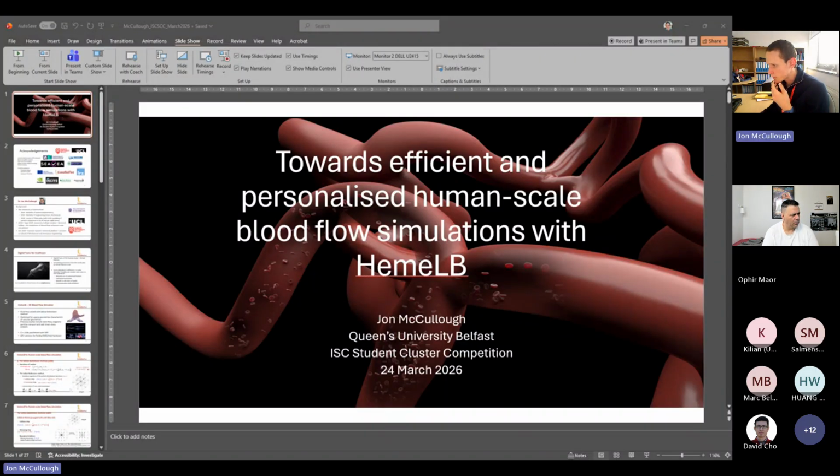Sergio, again, as a follow-up, report output file. Okay, so yes, use the simulation time. That's the actual time to conduct the simulation. The total time includes any initialization time. So total is from when you start the HemeLB process to when it completes at the end, and there will be some period of initialization. For the tiny bifurcation case, that might be a couple of seconds. For the virtual case, it could be 20 or 30 seconds. It depends on the resources used and the size of the domain.